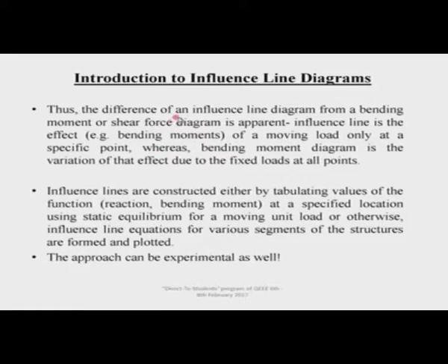Yeah. So, the difference of an influence line diagram from a bending moment or shear force diagram is apparent. Influence line is the effect, that is the bending moment, of a moving load only at a specific point, whereas the bending moment diagram itself is the variation of that effect due to the fixed loads at all points. This is the difference with the bending moment and shear force diagram. Although the book spent a lot of time over it, and they sometimes try to tabulate the difference, making the student feel that this is a very basic quantity of interest.